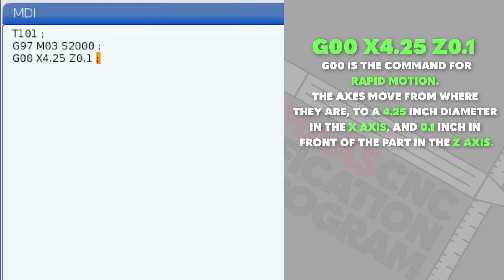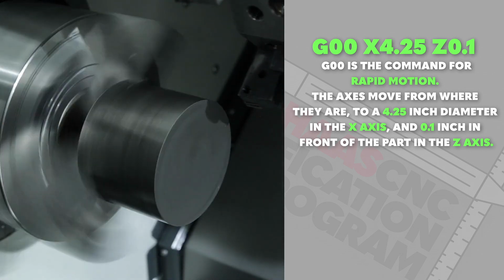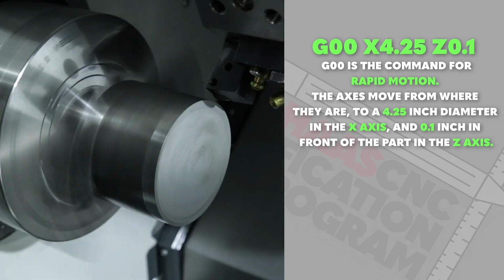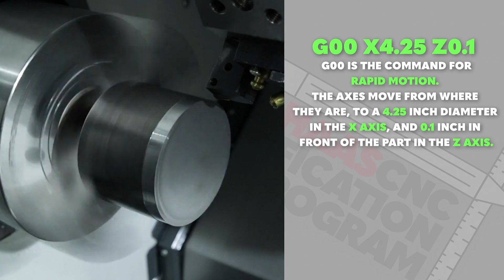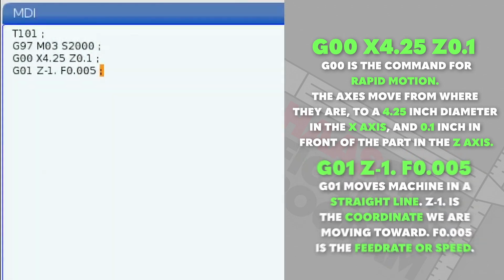G00 is the command for rapid motion. This tells the machine to move at its fastest possible speed to the position in the address code. So in this case, the X and Z axes move from where they are to a 4.25 inch diameter in the X axis and 1/10 of an inch in front of the part in the Z axis.